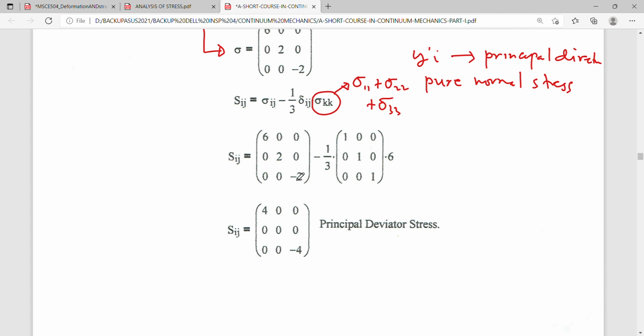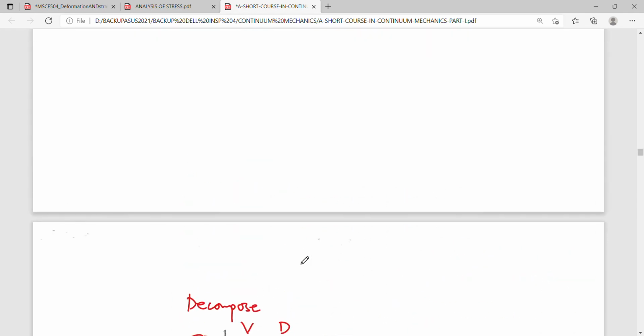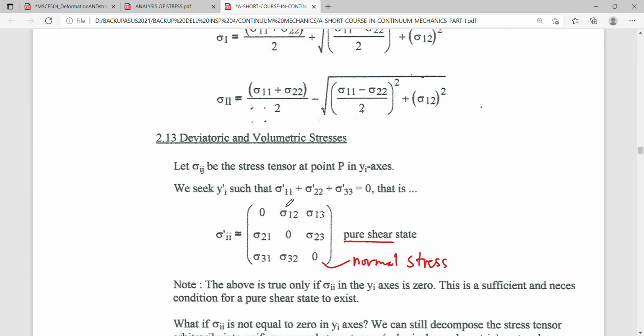And this is now your matrix values upon which, if we operate on this, you simply get this principal deviator or deviatoric stress. So if this is not a principal stress tensor, you just remove the word principal there. It's a simple deviator stress. And take a look. The sum of this is 0, as implied on the condition that this must be 0.